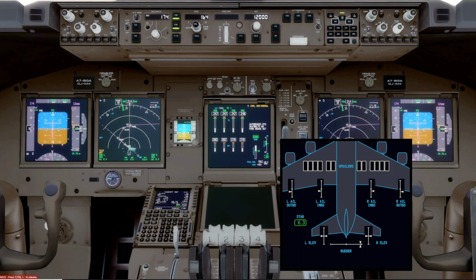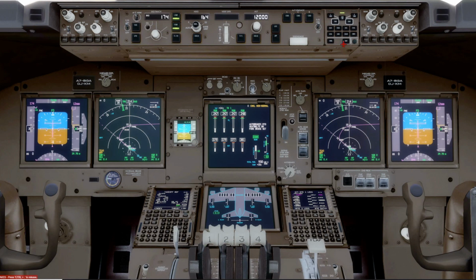And then on the rudder, we'd be holding the tiller when we do this. Full and correct movement, back to neutral. And then 2 left, again holding the tiller so the nose wheel doesn't move. And back to neutral. So we actually have a nicer representation on the Dash 8 of the flight control system. You can also see again that when we're at takeoff flaps, the flaps are drooping. That improves performance and reduces noise in the Dash 8. And then we can go ahead and blank that and go flight controls again. Blank it out. And then we could do our before taxi checklist.